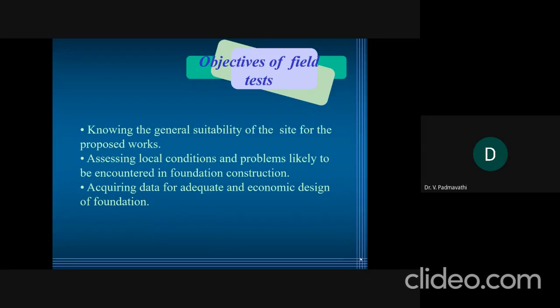That's why we need some sloping nature of the soil, let it be 75 degrees or 80 degrees. Sometimes the slope may fail also. So we need to know the local conditions of the soil, whether seepage is present, or whether it is possible to cut the soil in the vertical direction, exactly 90 degrees or 85 degrees like that.